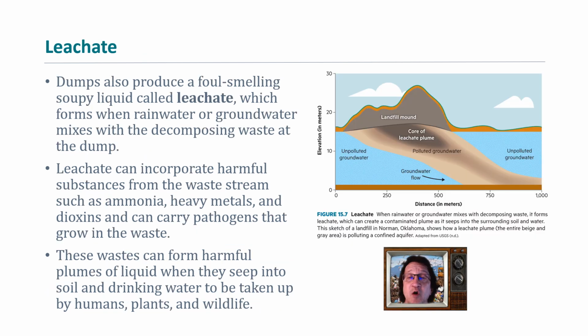So landfills don't only produce air pollution, they can also produce water pollution. The soil that a landfill sits over, if it is not provided with a barrier to hold on to water and a way to funnel the water away and collect it, that stuff will leak into the soil, and it will leak as what's called a plume, P-L-U-M-E, and that will travel in groundwater.